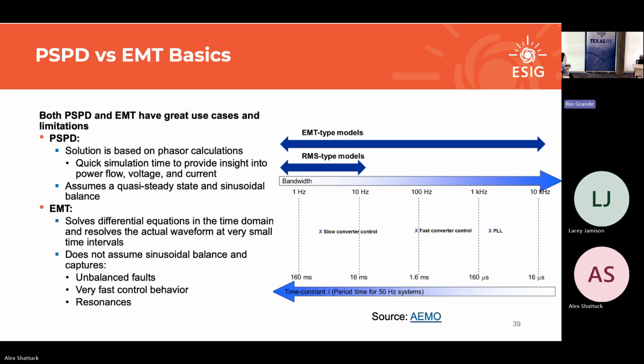And then that has all kinds of implications on the IBR controls, right? In terms of how they react to unbalanced faults in the system. When we're doing this sort of model quality testing or design evaluations, a lot of the time the worst cases are unbalanced faults, where you are applying a two-line-to-ground fault or something like that, and that causes a resultant overvoltage on the healthy phase and things like that.